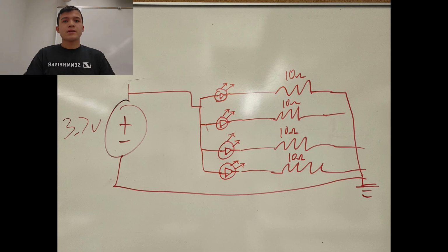For the lighting subsystem, I wired the LEDs in parallel with each other so that they all had the same brightness when the system is turned on. Each LED was then wired in series with a resistor as a means of controlling the current flowing into it.